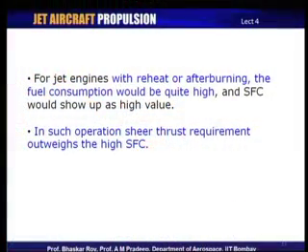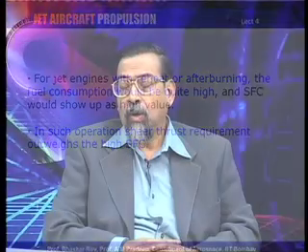Hence, we can summarize by saying that for jet engines with reheat or afterburning, it is expected that the fuel consumption would be high and the SFC would show up as a high value. In such a situation, it is normally expected that the sheer thrust requirement at that particular moment of operation outweighs the high SFC. You are sacrificing the fuel consumption for the immediate requirement of thrust production.